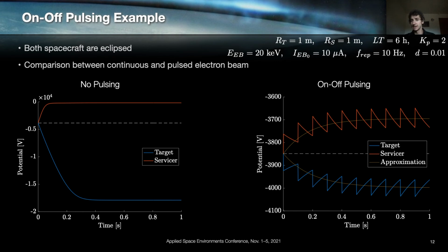And the second reason is that using a pulse beam current could actually be better from a signal processing perspective, because if you excite those X-rays and secondary electrons at a specific frequency, you could later on filter out other frequencies in your signal and therefore get a better signal for the one you're producing.